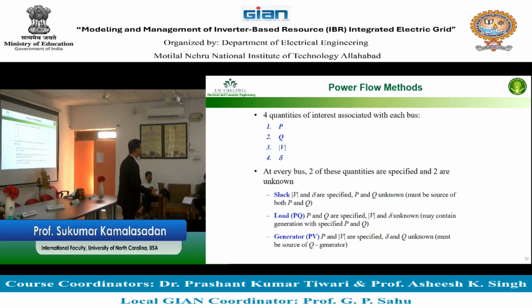So do you want to do any math to calculate that power? You already know that. But if there is a bus where no load is connected, I don't know what the active power and reactive power is. Do you need to calculate it? Yes, I need to calculate. So for some buses, you have the active and reactive power known, and for some you don't.